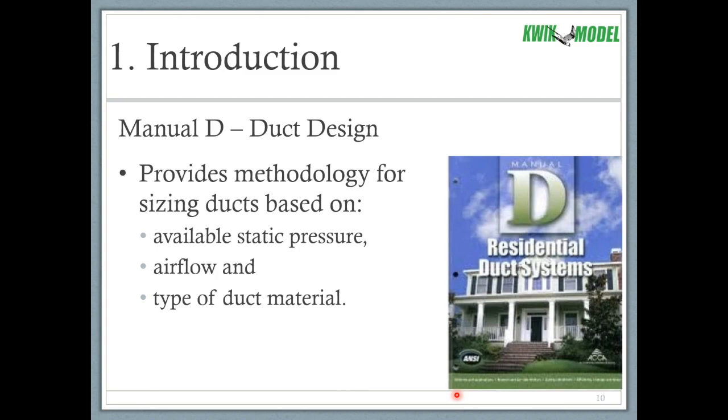So it might take you a size bigger to move air through a flex duct than through a sheet metal duct, because sheet metal duct is much smoother.